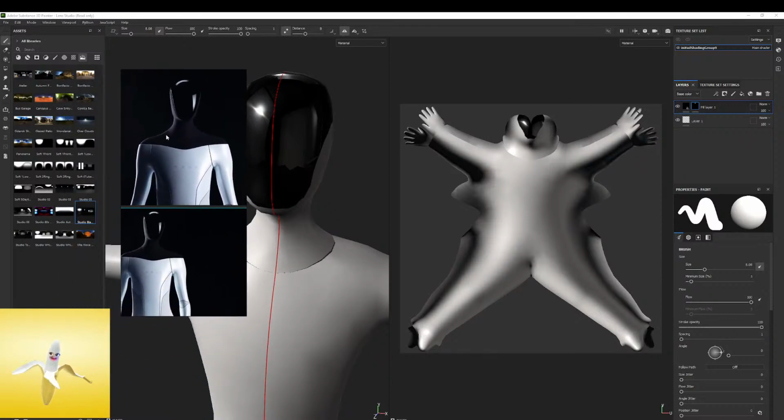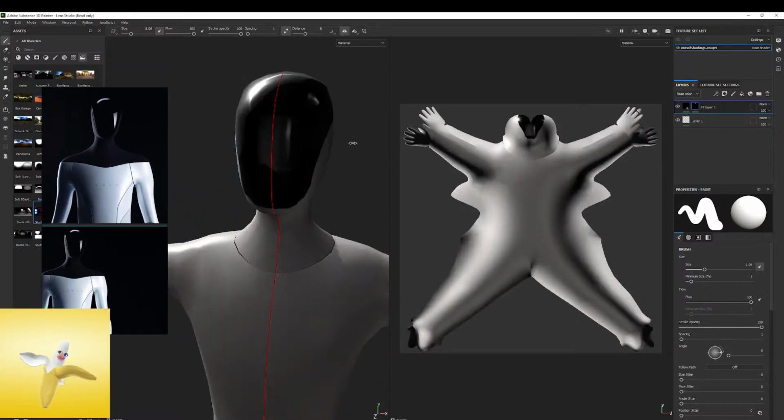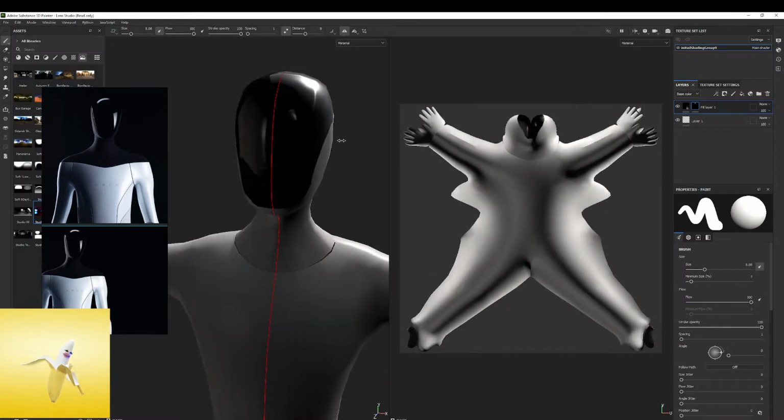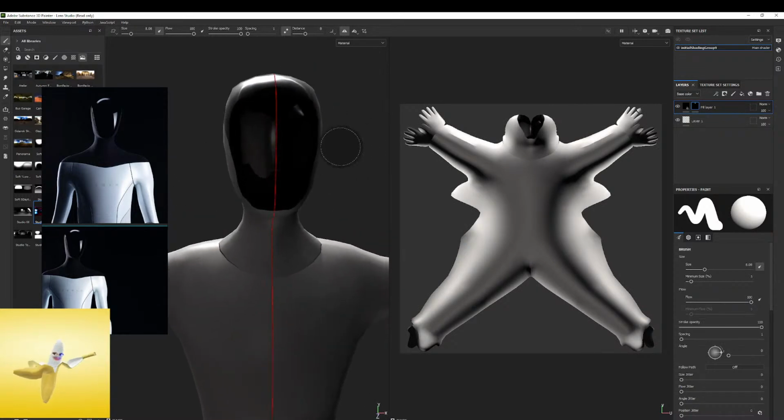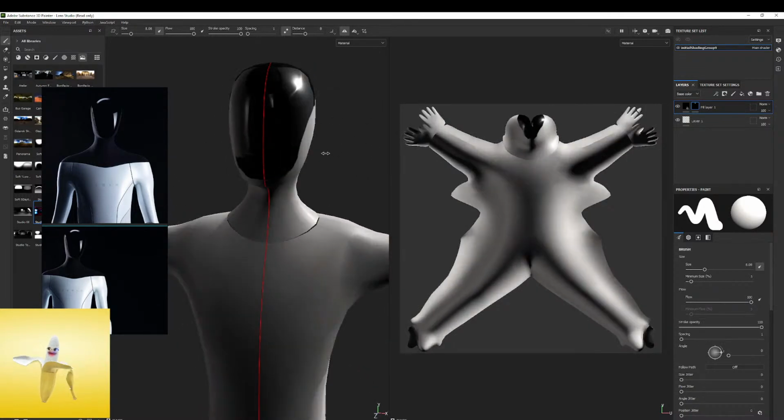In Substance Painter, you can actually upload your own images in here. These are called HDRI maps, which stands for High Dynamic Range Images. You can load up your own HDRIs. You could paint it in Photoshop. You could paint it in Procreate. You could take a photo of something, and then you could use that to light your scene if you wanted to change the color of those lights. They're not real lights. They're like baked lights into images, but the software will treat them like a light source, and we can rotate that image around to get the simulation of real-time lighting, which is fun.